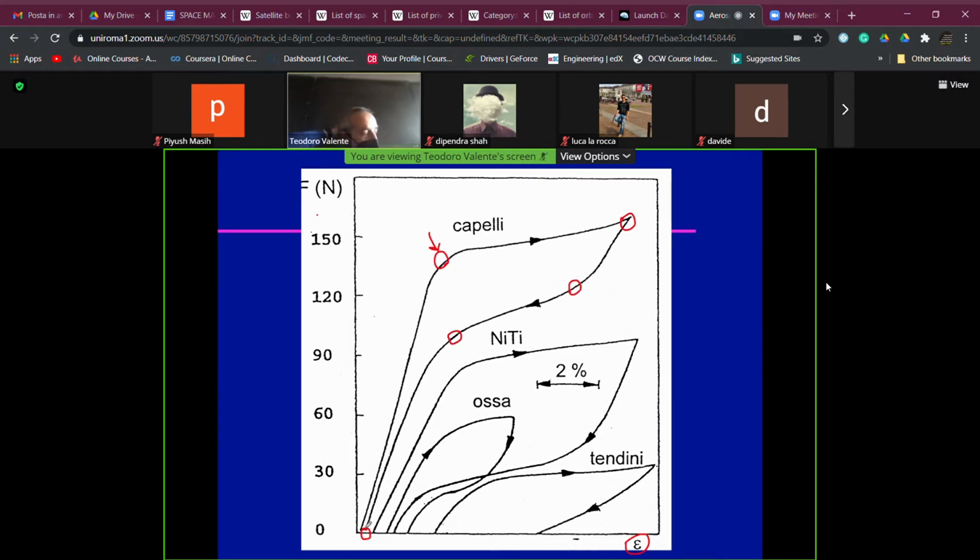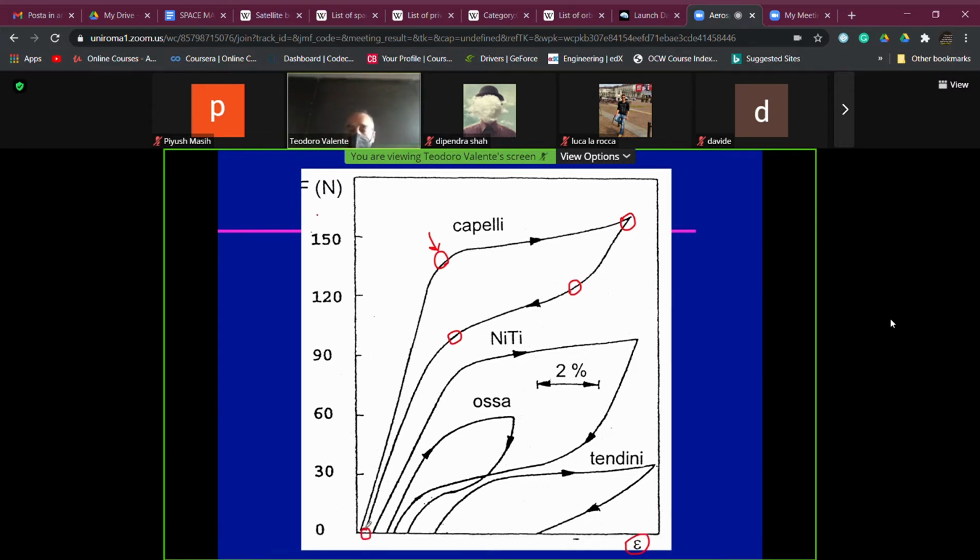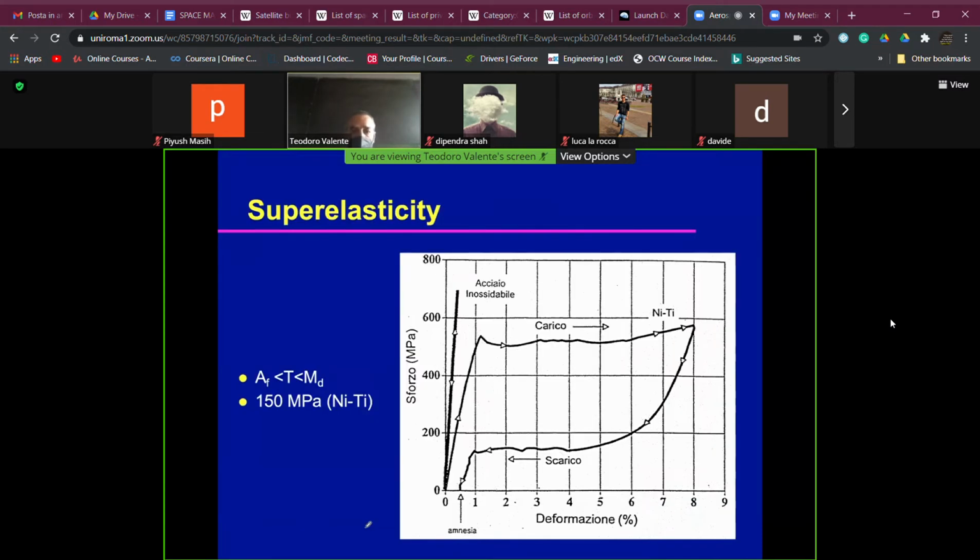In the case it is present, this is a non-recoverable strain, and we say that the shape memory alloy has a sort of amnesia, not recovering all the imposed strain during the transformation phases, which is again around a maximum value of 10%, like those we have already said for behavior purely related to temperature changes.